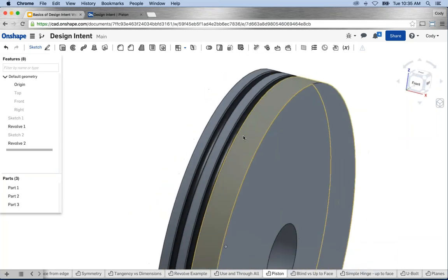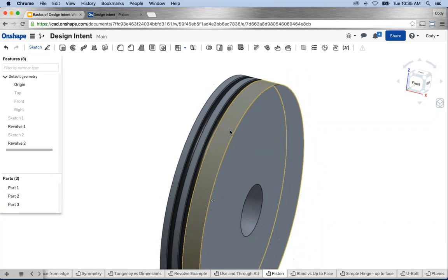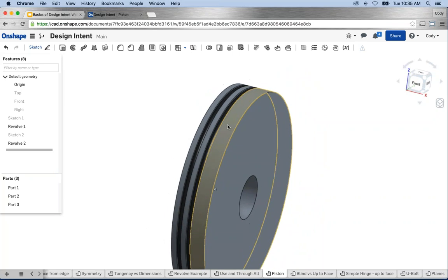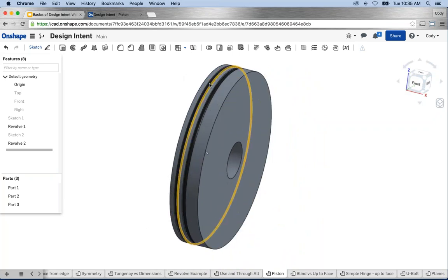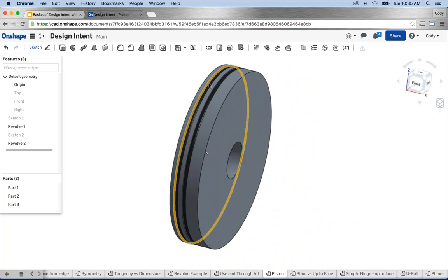And if you haven't done any multi-part modeling yet, it's definitely got a lot of advantages. One of the biggest is that I can build, for instance, an entire pneumatic cylinder and build different variations just by changing a few dimensions and have potentially dozens or hundreds of parts update all at once. So it is a very powerful modeling technique, but the important thing I want to take away from this is that all these lessons don't just apply to a single part. Here's an example where if I build the seals with the correct intent, they will automatically update as well.